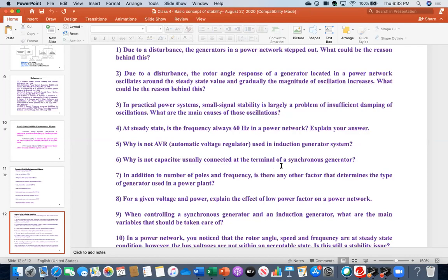I think everybody understands, right? Excuse me, sir. In the synchronous generator also, there should be power factor maintained always, right? Yes. To maintain that power factor, there is AVR, the DC excitation. You know that depending on the excitation, over excitation, under excitation, or normal excitation, power factor can be lagging, leading, and unity. So the power factor is maintained with the help of field excitation. Yes, sir. Thank you, sir.